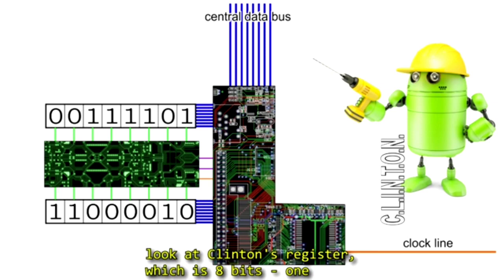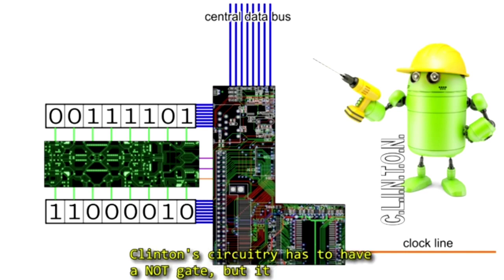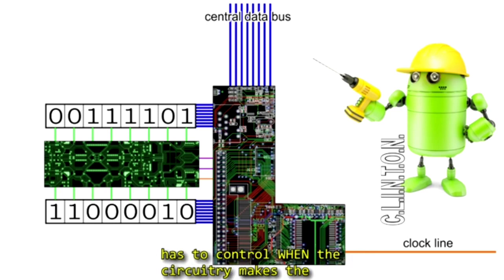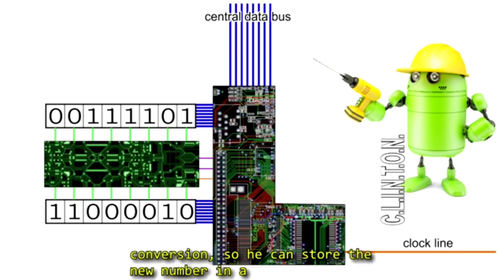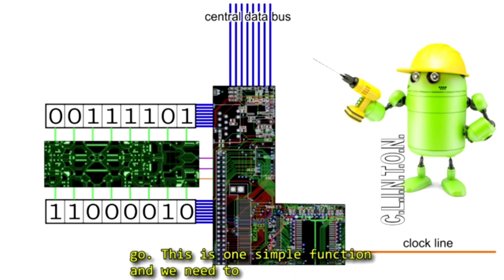Let's take a look at Clinton's register, which is 8 bits, 1 byte. Looking at just 1 bit, in order to do that, Clinton's circuitry has to have a NOT gate, but it needs to be combined with, say, an AND gate, because it needs to be driven by the clock cycle. Clinton has to control when the circuitry makes the conversion, so he can store the new number in a second register. So the second register also requires all of these gates like we did before, and then control lines to dump that register onto the data bus to pass it along to wherever it needs to go.